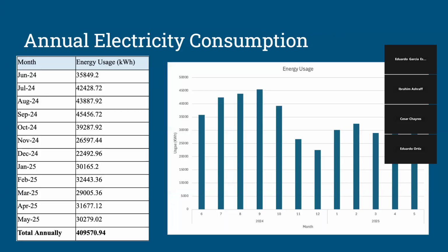So electricity costs are driven by both time of use energy charges and monthly demand charges based on the highest 15-minute load. Natural gas costs are based on the usage, and understanding this rate structure is important because demand reduction and energy savings affect cost differently.